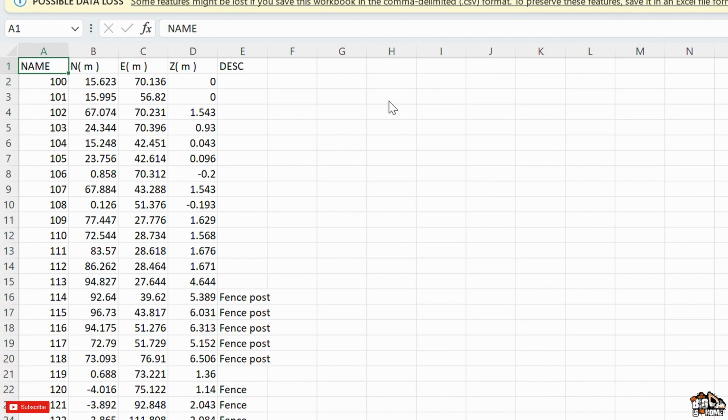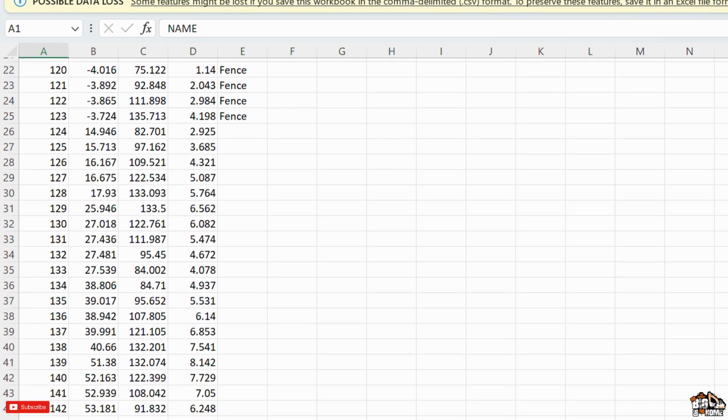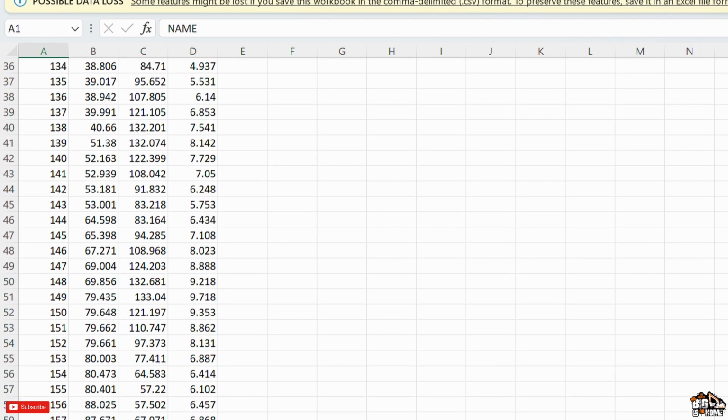So in this little box here, with the controller that you saw me with the total station, it's recorded all the points. I will save that now to a USB stick, basically in a CSV format. You can see on the screen here, it's just recorded as numbers and north and east positions and elevation. And then I can load that into the software that we're going to use. I use it purely for volume calculations for cut and fill.